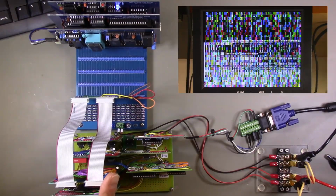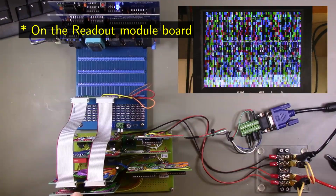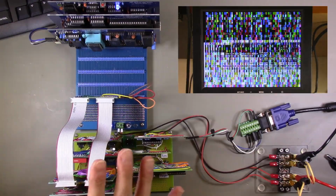And the thing that I tried first was to use 74ALS163 counters on this board. And my hope was, cross fingers, that will eliminate the ground bounce issues that I think are causing these glitches. All right, so what I'm going to do is replace the 74ACT163 counters on the readout module with 74ALS163 chips, and then we'll power up again and see if things improve.